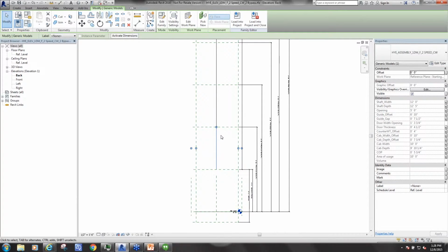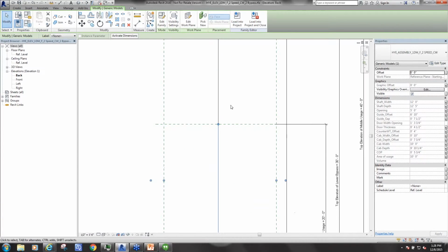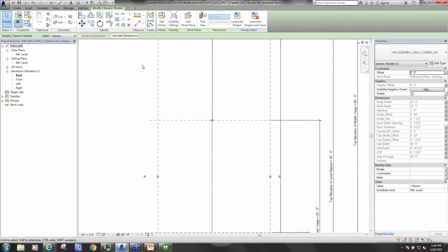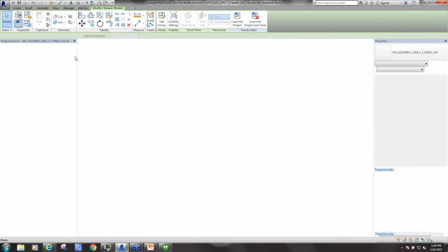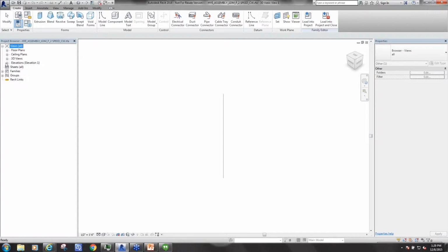The last thing that we added in was this notion of a graphical offset. Oftentimes in Revit, our view depths are not necessarily at 0. In our project, our view depth is -1'4", and we need that in order to show our curtain wall facade the way that we want it to. But if you're thinking in section and I have a floor plan that's cut up here at 4 feet, and I go -1'4", and I'm supposed to be showing an area of bypass, all of a sudden I'm creeping into this area that's going to show me my active cab.